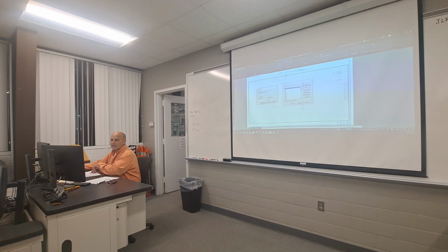In the box it says drawing units, not paper units. Paper units is still gonna stay 1. In the box that says drawing units, that is where your scale factor goes. We used to call it our magic number. We used to have to set up a dimension style in AutoCAD prior to like 2009 or 10, somewhere. We had to set up a dimension style for each scale that we used. So just like we go through and set up our dim style, and we go through all those pages, making little changes that I do for you in your classes before we come in.